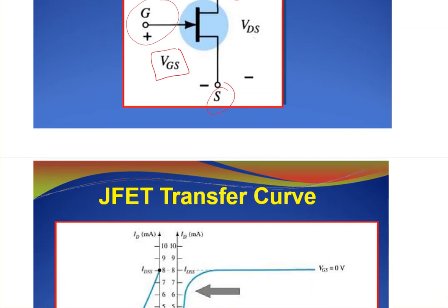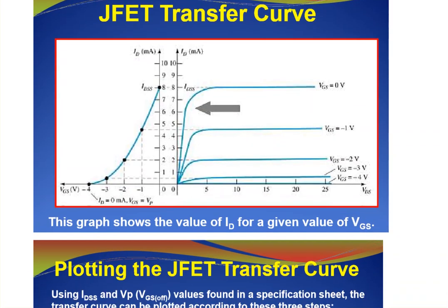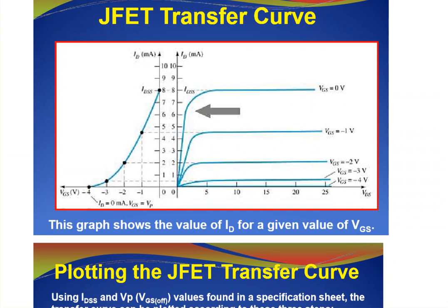So we have what we call the JFET transfer curve, which means that if I have these characteristics for my JFET, can you draw for me the relationship between ID and VGS? Of course we can do that. It's so simple. All you need to do is draw another axis that is parallel to this ID axis here and has the same numbers. And we will look for the value of VGS, which is minus 4, as an example. I know that for VGS equal to minus 4, the value of ID is equal to 0.